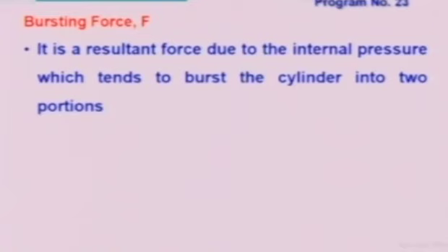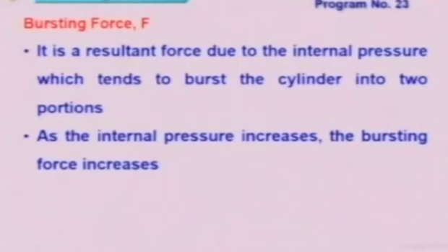Now the next one is the bursting force. What exactly is a bursting force? It is quite common sense. We take a pipe and subject it to some internal pressure. As the pressure goes on increasing inside, the tendency is that it forms a resultant force within the cylinder, and then it tries to burst the cylinder into two portions. So what you need to understand here is that it is nothing but the resultant force which develops due to internal pressure, and this particular force tends to burst the cylinder into two portions, and that is called the bursting force. So you need to understand that as the pressure increases, the bursting force also increases.